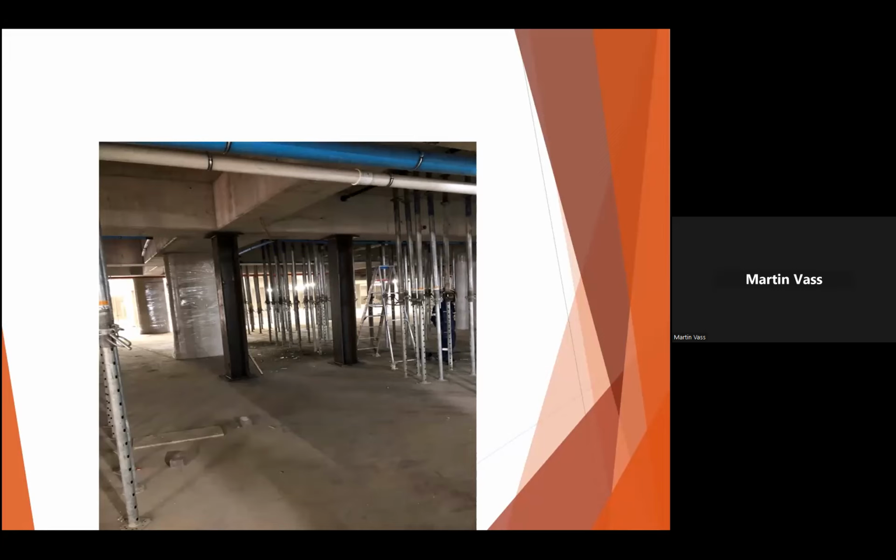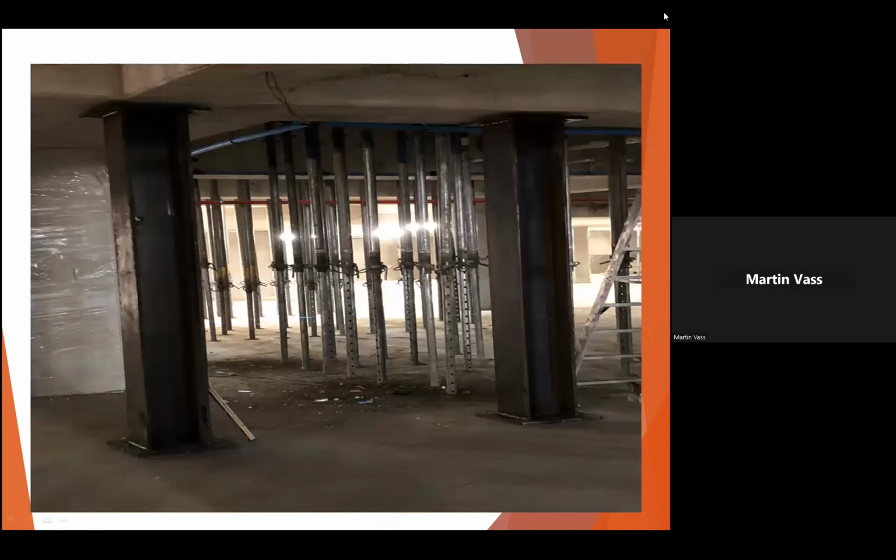So this is very much an ongoing investigation at the moment. I'm not going into the ramifications of how you transfer the load to these columns. That will be a separate seminar, and will take some hours. So these are going to be in place. They are going to take the load, transfer the load to these steel columns, and they will then carry part of that building which the transfer beams are not carrying at the moment. So that is our first exercise. Very much ongoing, lots of discussion, lots of meetings on this one. Those are the steel columns again, and the props are still in place. They'll slowly be removed, and these steel columns will then take the load.